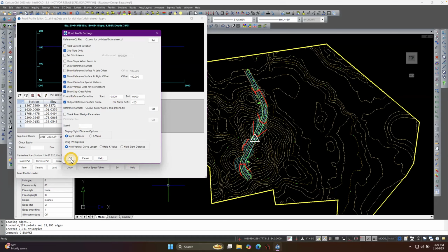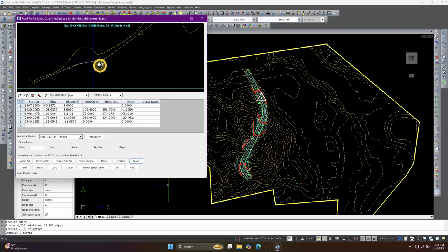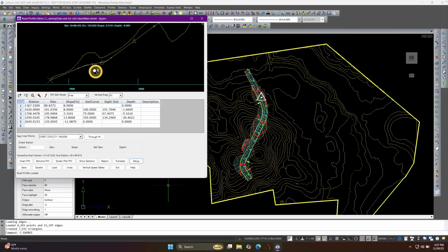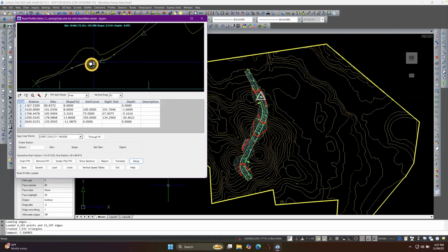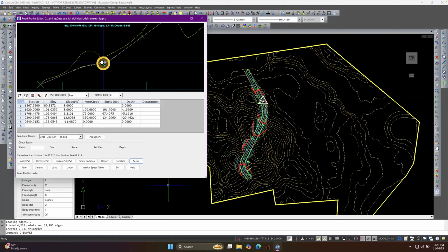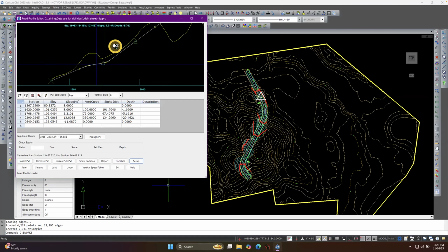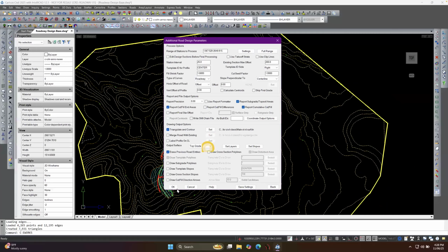That's how you can use the sections once you've designed that template, it actually processes this. But see, I've now lost my low point, so I would no longer have to worry about putting a gutter point there because that's no longer a sag curve. It doesn't dip below where it starts. It's always on the upswing, even though it's a vertical curve that goes up instead of down. So if I save that and exit, let it process.